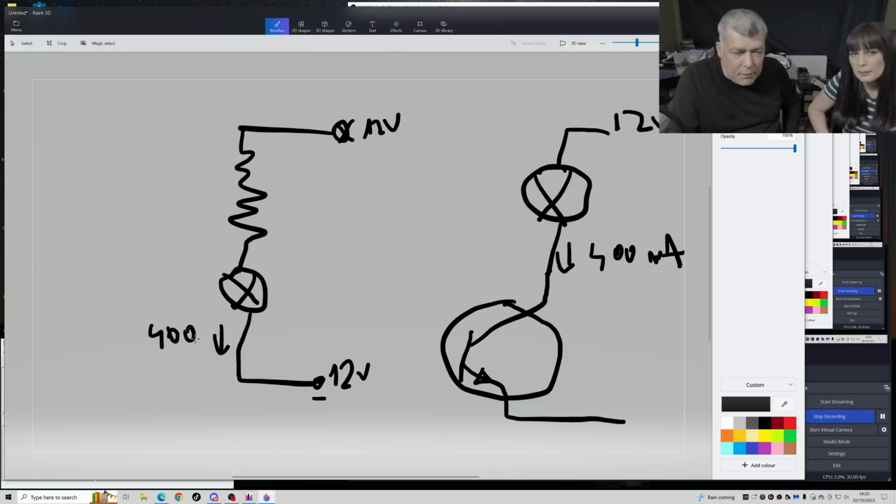But with 400 milliamps, what was the value of the resistor? You tested. What was the value? It was 18. 18 ohms, right? So a current flow of 400 milliamps, in series with the light bulb, means I should have an 18 ohm resistor. So what is the internal resistance from the collector to the emitter if I have 400 milliamps current flow? It will be 18. Exactly.